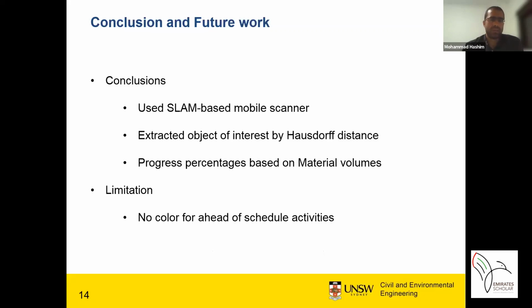In total, as the conclusion of this work, we used a SLAM-based mobile scanner, which is new instead of the static one. We extracted the objects of interest, which were walls, using Hausdorff distance. And we also calculated the progress of work based on the material volume, which later will help us in procurement management and allocating resources. There are also some research limitations, such as not applying the color code to the ahead-of-schedule activities, which we will work on in our future work.